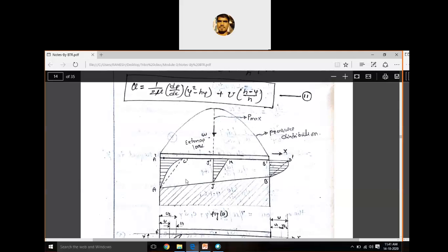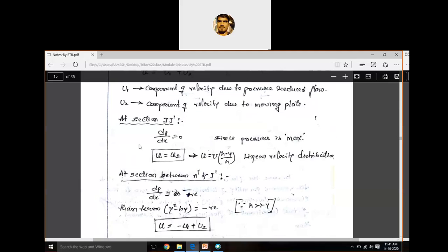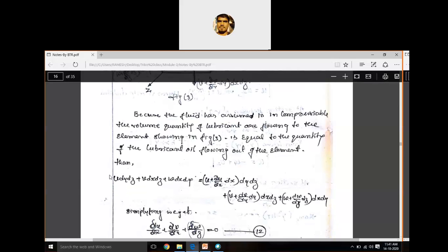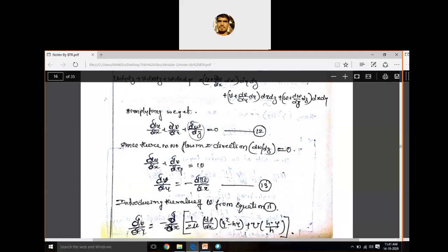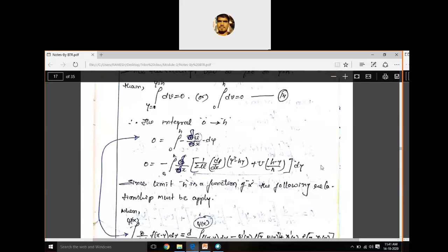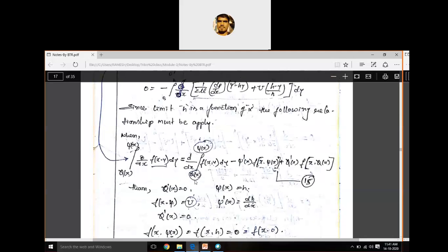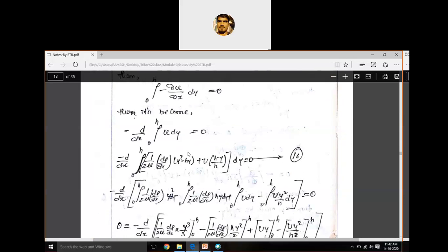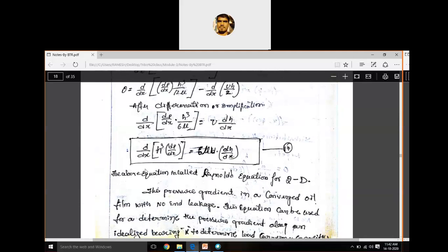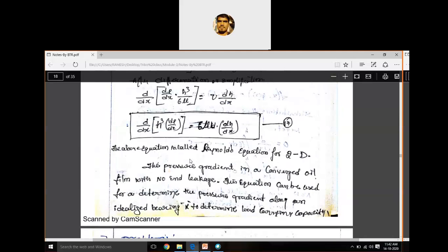This is a plate and taper surface, how the velocity and pressure change I explained, and these are the cross sections. And finally for discharge, whatever amount enters is equal to the discharge, that is velocity into area, we got the discharge. And we considered all the elements u, v, w as velocities in the x and y directions, the z direction we neglected, and finally got this. Substituting this and applying integration, integration is not possible, it is not in an integratable form. So this equation we convert or simplify using this. This is what we got from the data handbook. Here compare and simplify, we got the integratable form, and this equation 16 is integratable, and apply integration, rearrange and refine. Finally you got the Reynolds two-dimensional equation. Equation 17 is called the Reynolds two-dimensional equation.